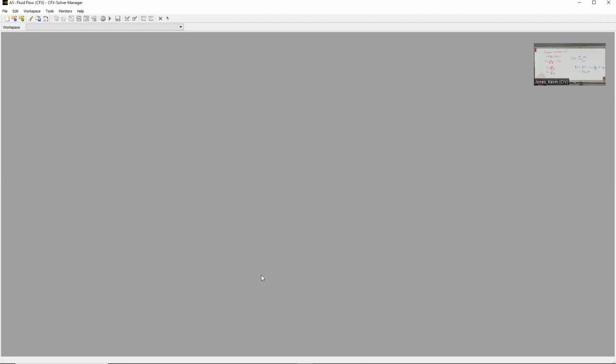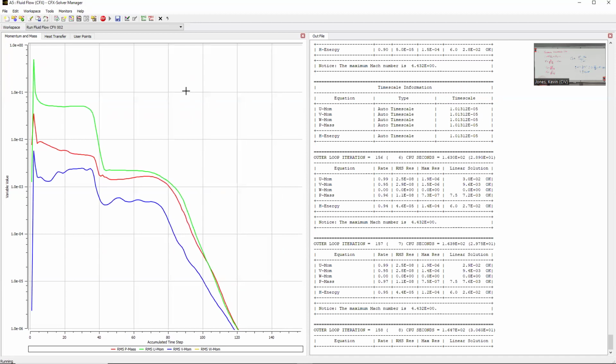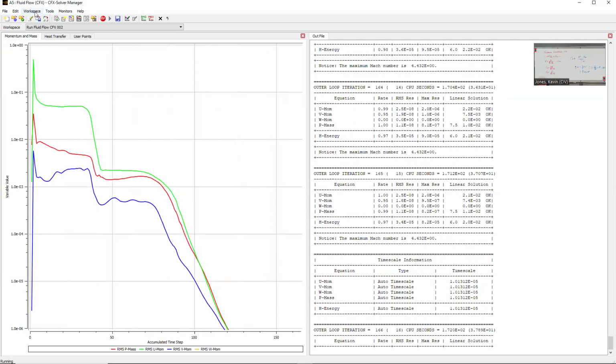The first thing it's going to do is load in the old solution, and it's going to immediately redo the mesh. And we'll immediately see W momentum show up since it's got multiple cells in the third direction. I'll tell you, this tool works okay in 2D.